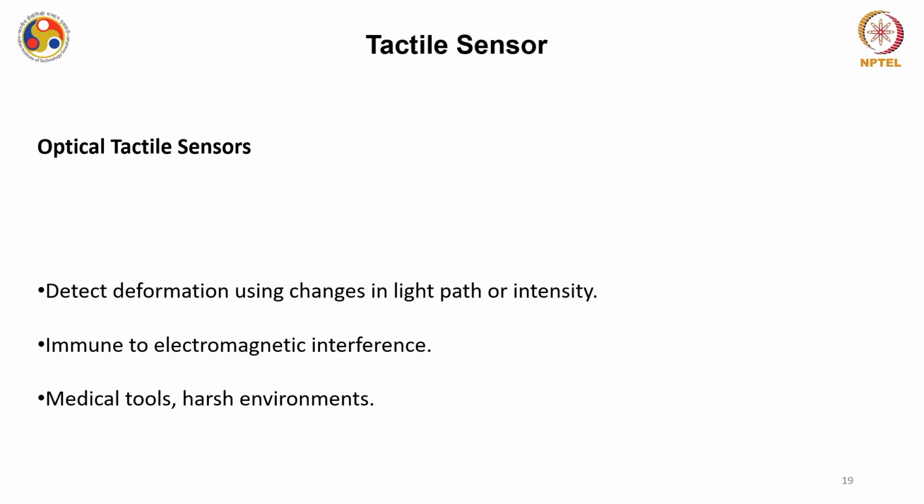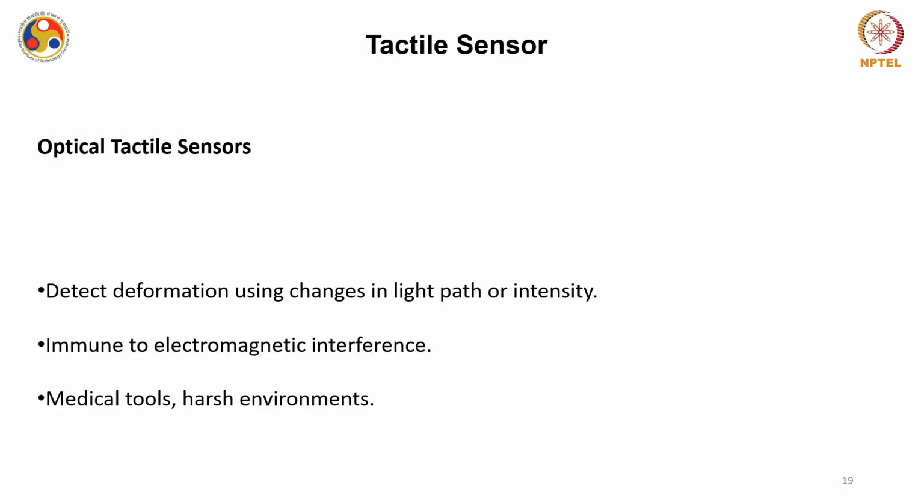Usually they are based on optical phenomena, on photons, so they are mostly immune to electromagnetic interference. That is why sophisticated applications like medical tools are based on optical tactile sensors. Another good advantage is that they can work in harsh ambients, where you want little effect from temperature or moisture conditions in the ambient. In those conditions also, optical tactile sensors are very helpful.